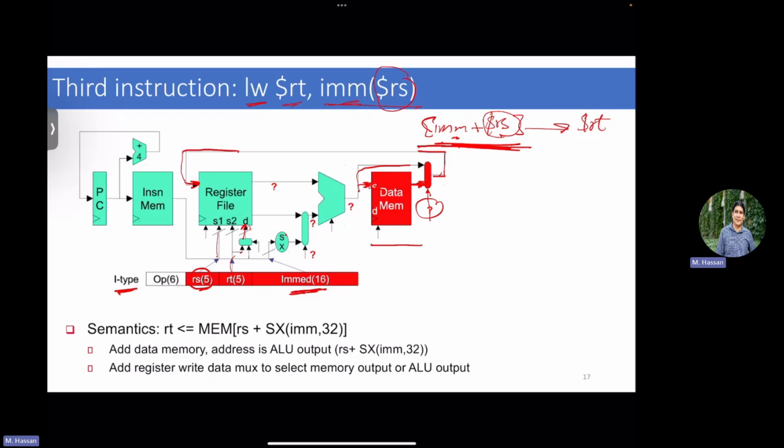Are we currently ignoring that the data transaction could take a long time? Yeah, 100%. In our discussion of control path and data path, we're assuming this data memory is just accessible while you're doing this. One reason why this is valid is because we never discussed how many cycles I take here. We say this is the simplest single cycle processor where you take all the time you need to bring in your data, right? We didn't even discuss pipelining, which means if the data here takes 100 cycles, I'm just waiting until I bring it in, because we're executing one instruction at a time.